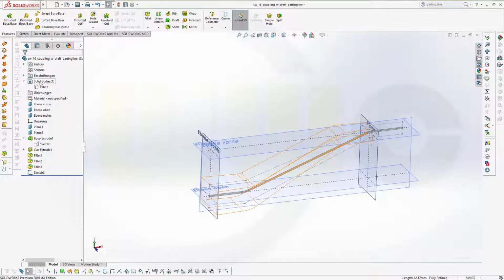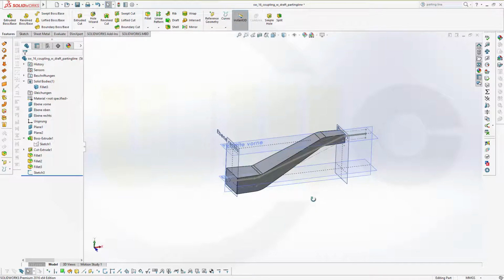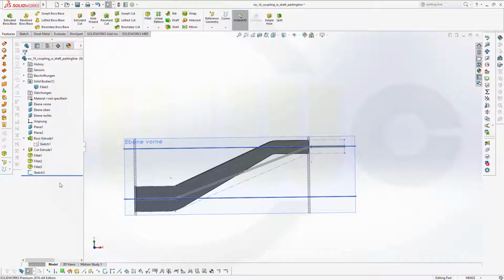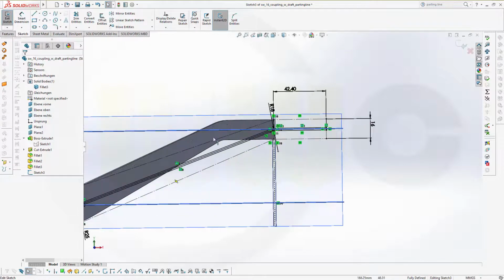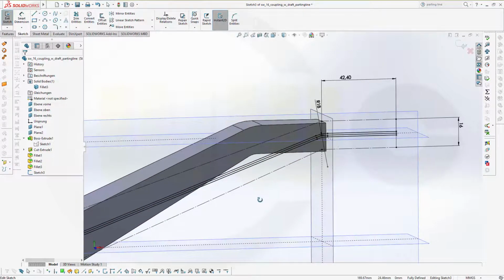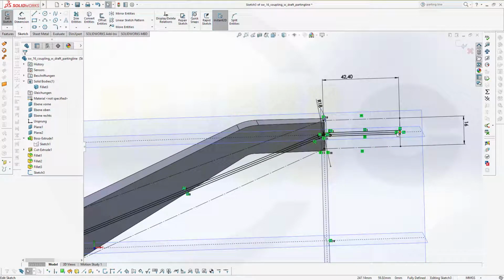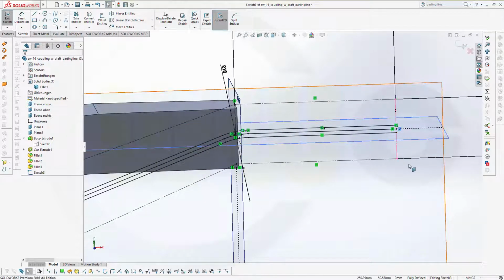and now I can do my parting lines. Let's show our solid body. That would be this one. Oh, I made a mistake in the sketch, obviously. So go to the sketch, edit it. Because that point should be right in that plane. So let's delete this one. Take a look.